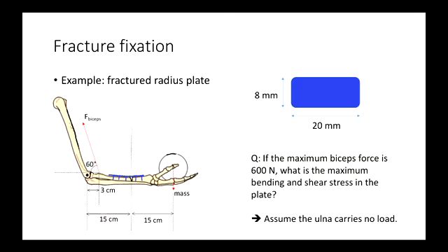So I said before I like to work in millimetres. 6 times 30. And is that a positive or negative moment? Positive. Subtract M times its lever arm, because that's acting straight down. M is 30, so 300. Right, and that's clockwise, so negative.